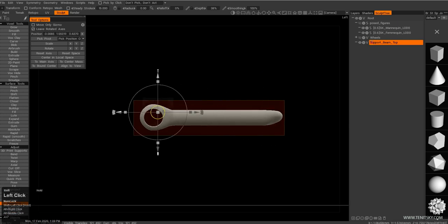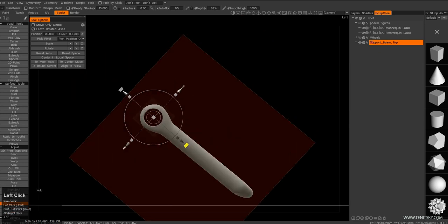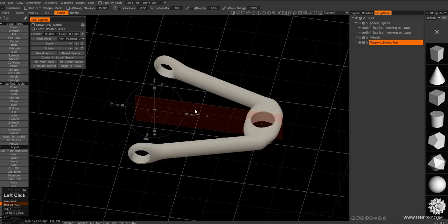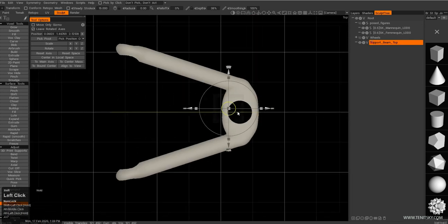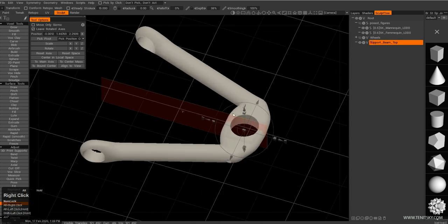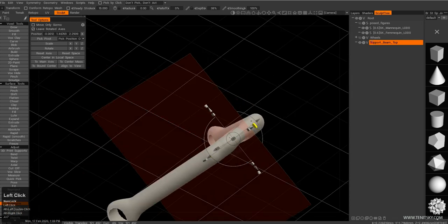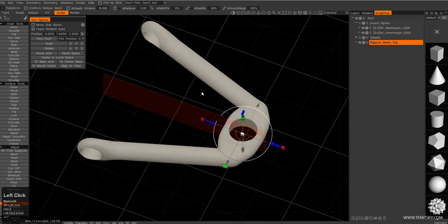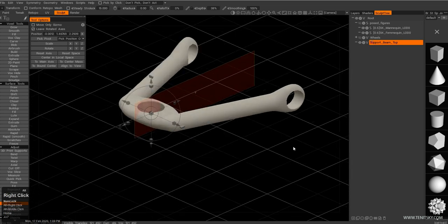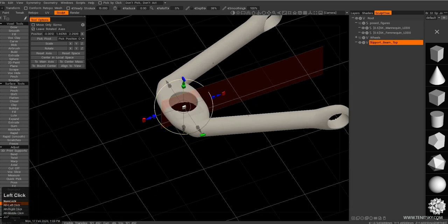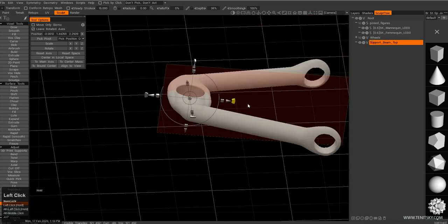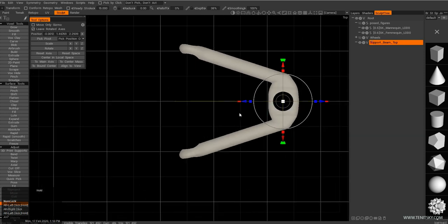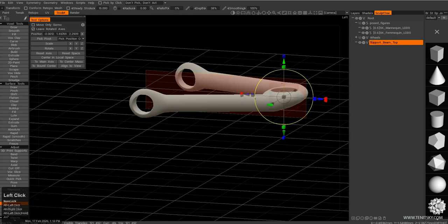So this support beam will go up and down only in one axis over here, but in the middle here it is a ball joint, so it will have the ability to rotate all around in any axis. It has a limited mobility because it's supported by the steering rod, by the support beams, and the shock absorber also plays its role. But this is essentially our basic setup for the beam.